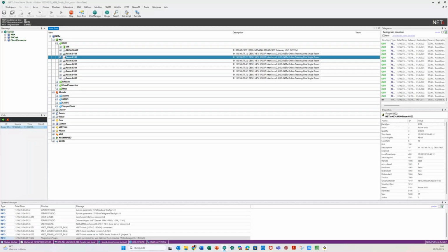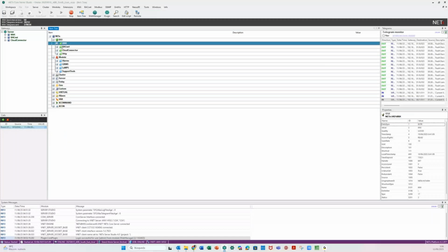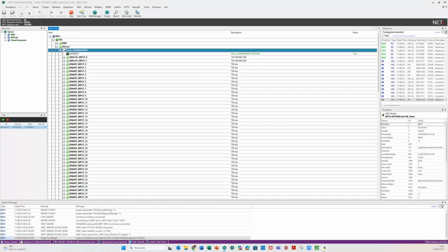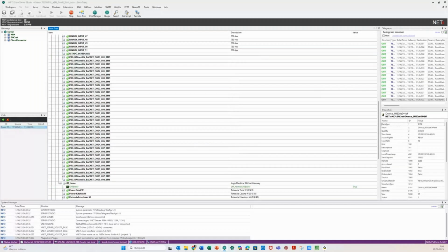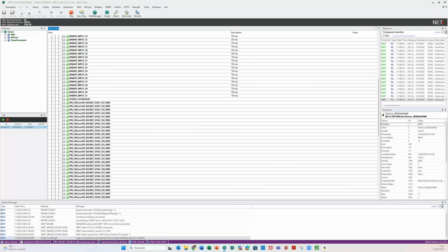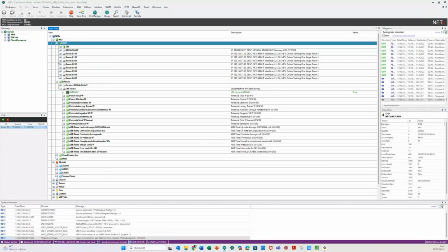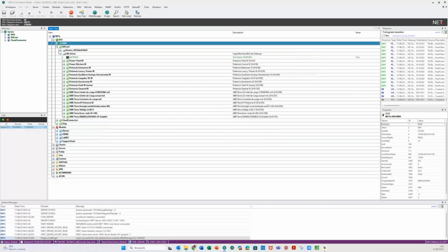Then we also implemented the BACnet devices. So we had 2 examples of BACnet devices here. One BACnet driver with inputs and outputs. It was really simple to do because it was automatic. And then KNX, we said, is semi-automatic because we had to export from ETS and then import here, but it was really easy to do. Then we had some tables to handle this, for example, the Telegram definitions, as you may remember.